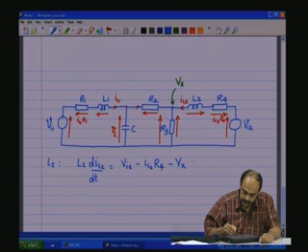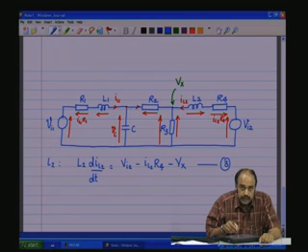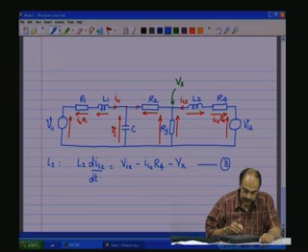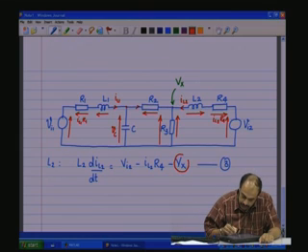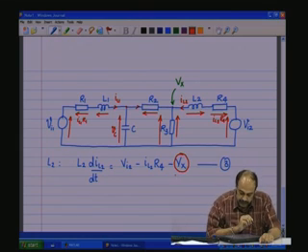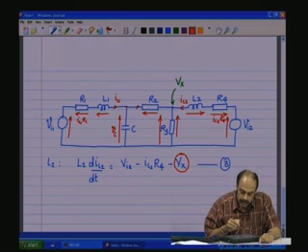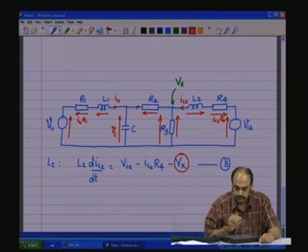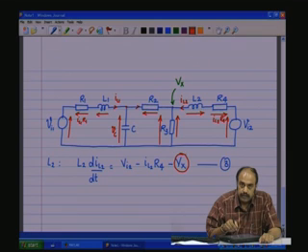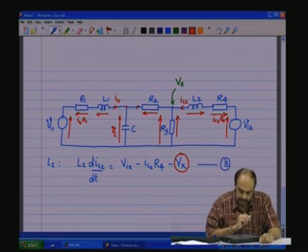And the third equation is this, which is revolving around the dynamic element L2, which is L2 dIL2 by dt equal to Vi2 minus IL2 R4 minus Vx, and Vx again is the intermediate variable, which is expressed as above. So, all three equations are expressed as functions of input variables and state variables only, the intermediate variable being expressible in the form of state variables.